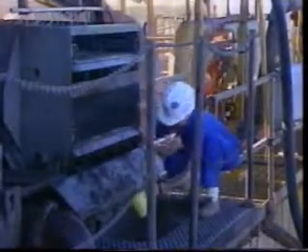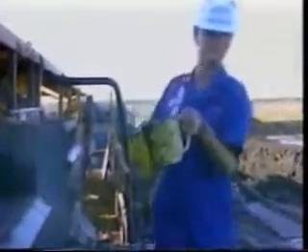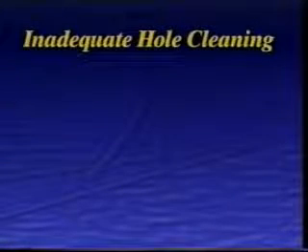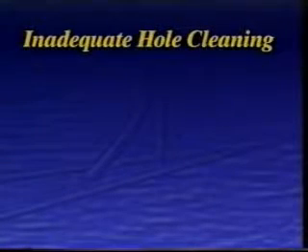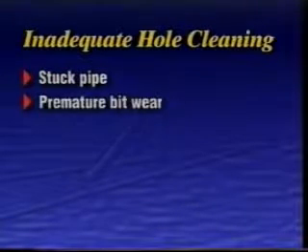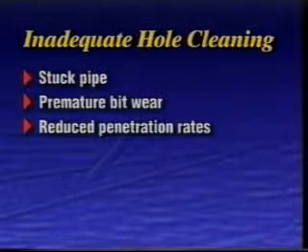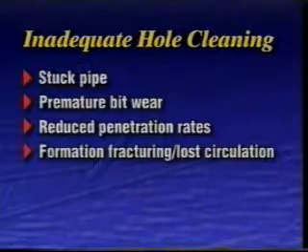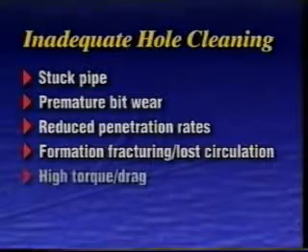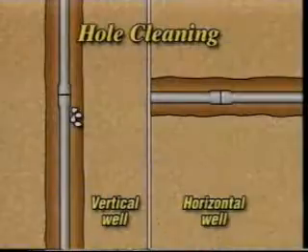Horizontal and high-angle holes also require special considerations with respect to the drilling fluid program. One of a drilling fluid's key functions is to remove cuttings and clean the borehole. Problems that may result from insufficient hole cleaning include stuck pipe, premature bit wear, reduced penetration rates, formation fracturing and lost circulation, and high torque and drag.